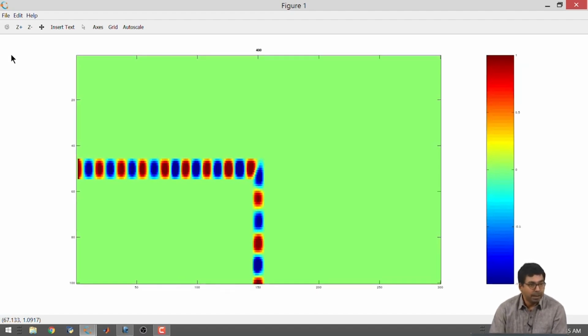Clearly, this waveguide is single mode. So, what happened is, a portion of it started going through the 90-degree bend, and it did not change the mode configuration. But normally one would say that, look, it is not a very conclusive thing. The only thing you can say is, you are getting light from this side and it forms a specific mode pattern, and the light is coming from the other side, it is forming a specific mode pattern.